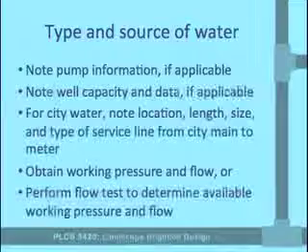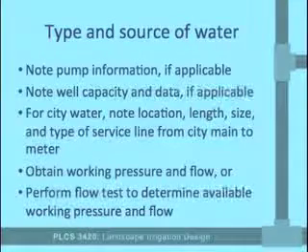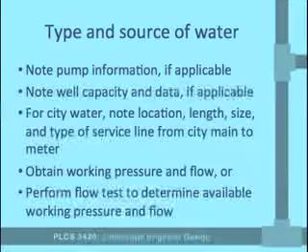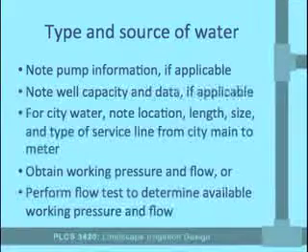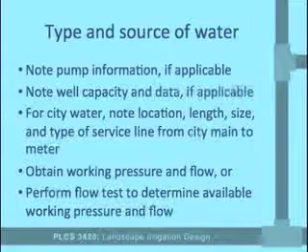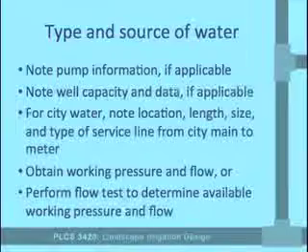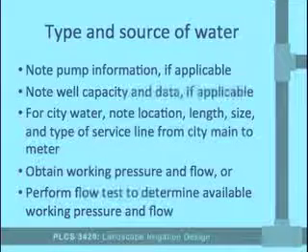If the water source is from a pond or a stream, it's likely that that water will be pumped with the use of some kind of an electric pump. So you want to note that information. If the water source is a well, you want to note the well capacity and get any well data that might be available, flow rates and so on.